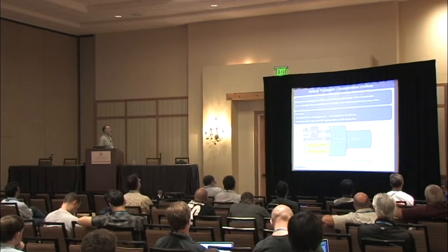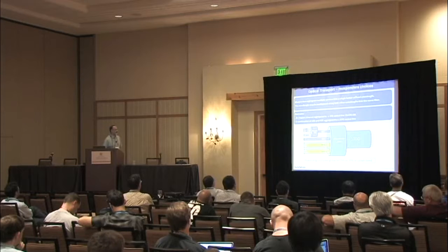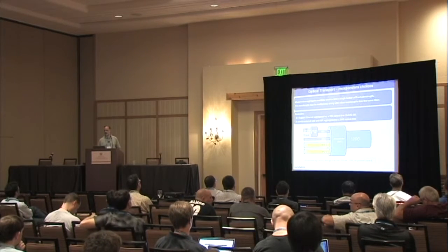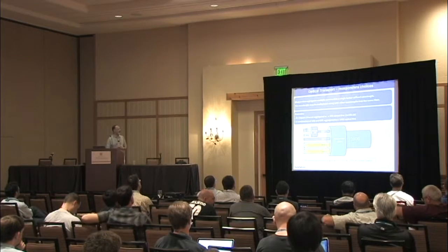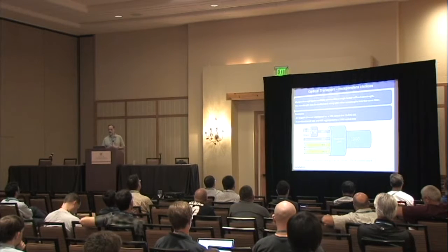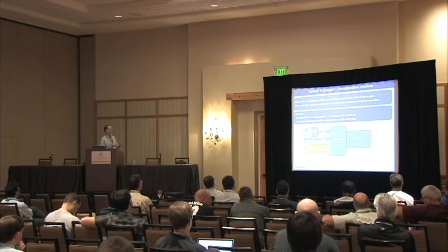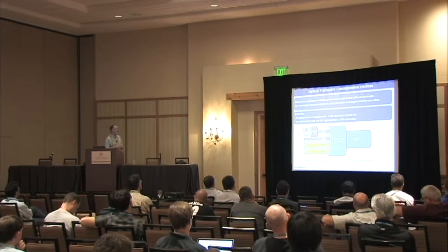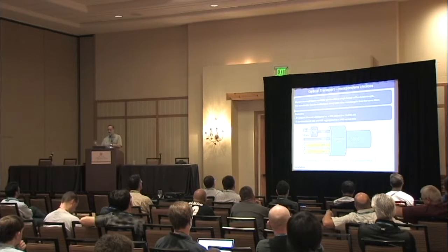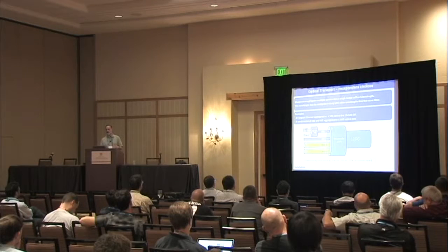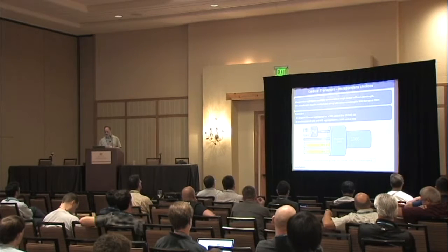Muxponding. Muxponders, as you guys know, aggregate multiple services into a single, better utilized wavelength. And that wavelength then goes over the WDM, through the WDM multiplexing scheme, and goes on the fiber. Typical example, take an 8 gigabit Ethernet aggregated to a 10 gig optical line. And if you want to go next in line, you basically can combine the 10 gig Ethernet with some 40 gig, generate a 100 gig line, but that's the idea.